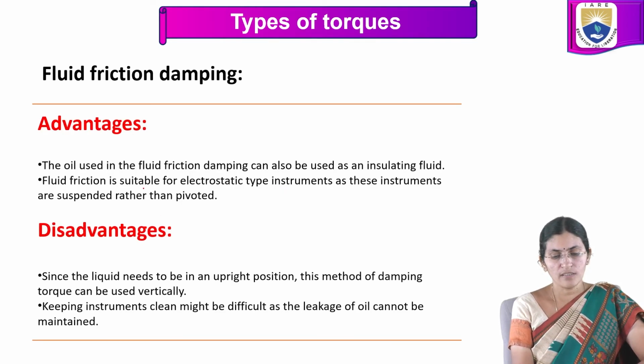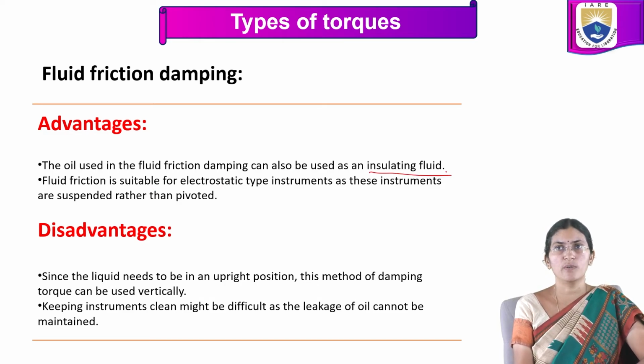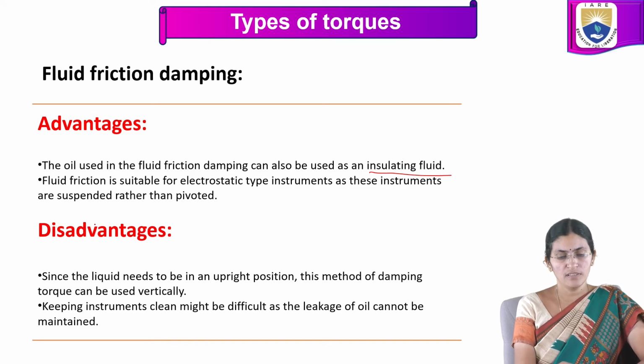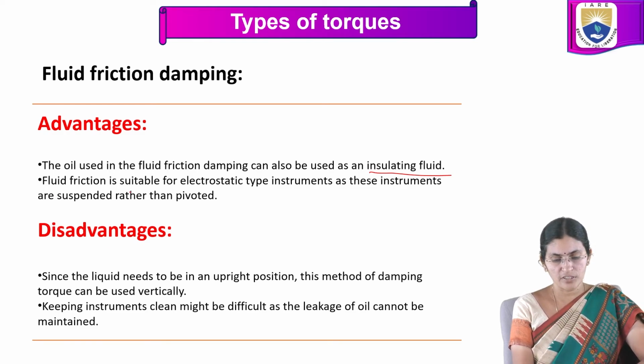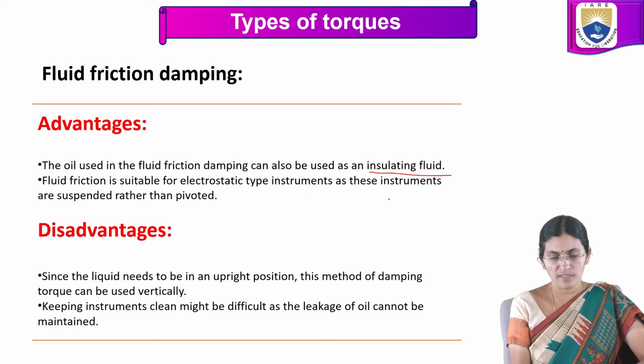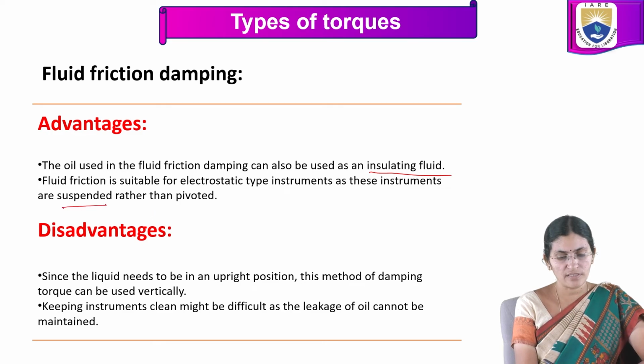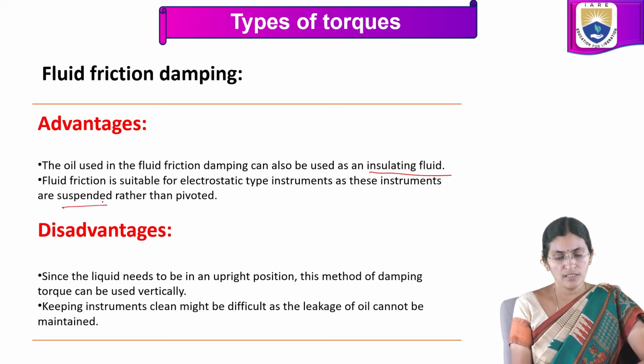Advantages: the oil used in the fluid friction damping can be used as an insulating fluid also. That is, it also acts as a dielectric medium. Fluid friction is suitable for electrostatic type instruments. As these instruments are suspended rather than pivoted, that means they are vertically mounted.